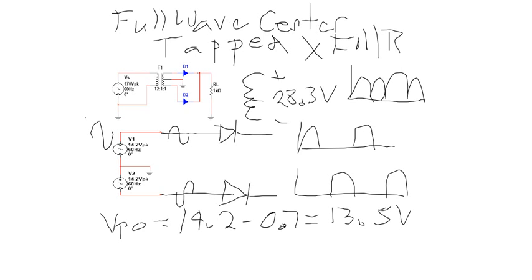So I've lost half my peak voltage here. Now I can get it back if I wanted to. Instead of making this a 6-to-1 or a 12-to-1 transformer, I could make it a 6-to-1 transformer with a center tap, which means a 3-to-1 on each half, and that gets me back up to my 28 volts. So all I've got to do is change the windings, or change out the transformer with 1.5 times the windings.